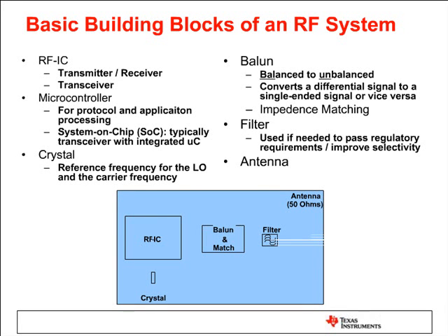We've got our 5XX core. The crystal, in the case of the CC430, runs off of anywhere between a 26 and 27 megahertz crystal. It does have a balanced output, so if you have a single-ended antenna or an unbalanced antenna, then you have to have the circuit that matches the impedance to that antenna, and so we call that a balun, and it effectively does the impedance matching between the antenna and the balanced output or input of the radio.